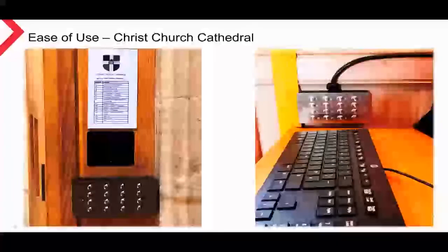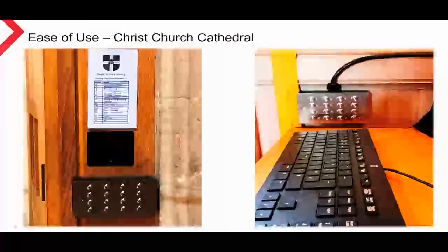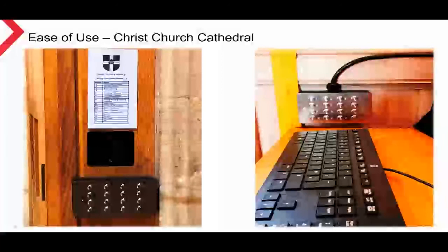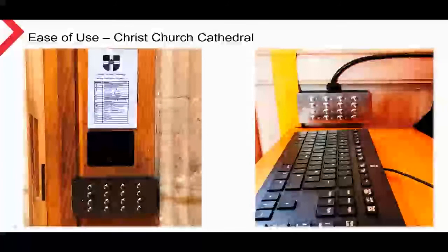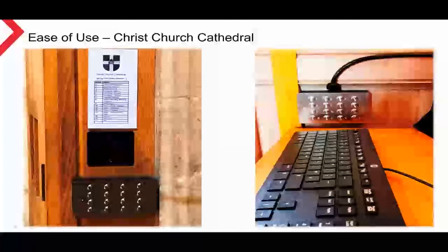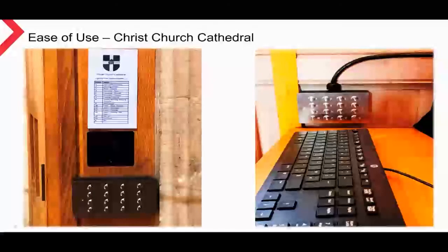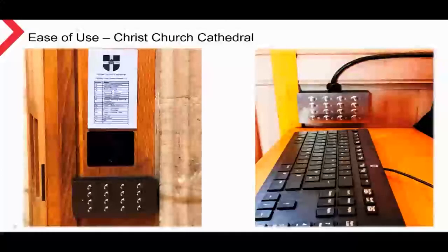Each panel consists of 16 buttons. Button 1 brings all lights up to 100% for cleaning and maintenance. Buttons 2 to 13 recall pre-programmed scenes, as I described earlier. Button 0 turns all the lights off, and with the up-down arrows, you can raise and lower light levels across all luminaires. On the push button, an LED illuminates when the button is pressed to identify which scene is currently active. The LED illumination is tracked and applied to both panels. A written list of button numbers and associated scenes was made available for reference or to act as a reminder.